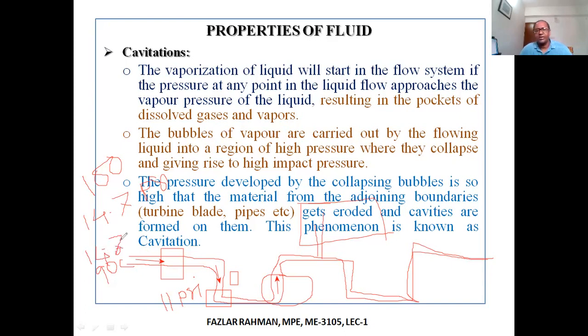So it will not boil because temperature is not 100 degrees. If it's 100 degrees, then it will boil. But it's flowing down, coming down. When it comes over here, for any reason your pressure inside the pipe is reduced. Say pressure is 11 psi or 11.5. Temperature is 90, the same temperature. But due to the decrease in pressure right over here, the water or fluid might boil.